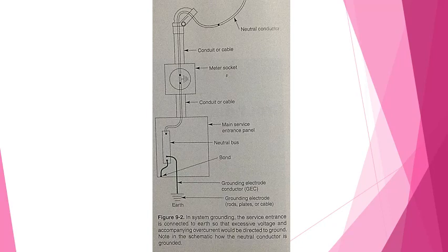In the previous chapter, we learned about the dangers of short circuits and ground faults. In either case, without proper grounding, an unwanted electric current could be induced in the system over its exposed portions. Proper equipment grounding would carry this unwanted current back to the device or back to the service panel.